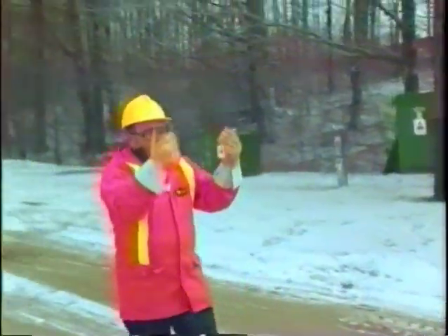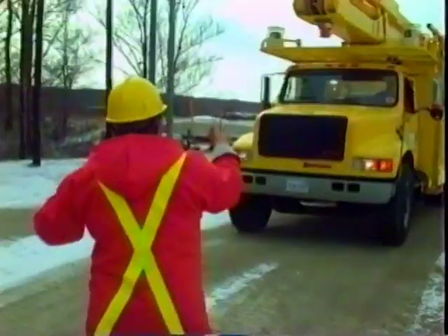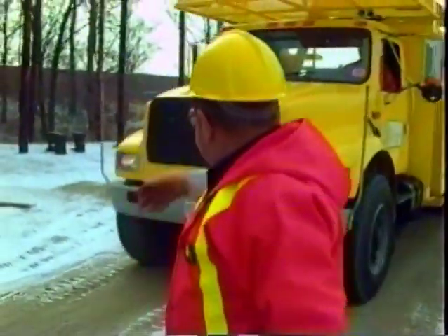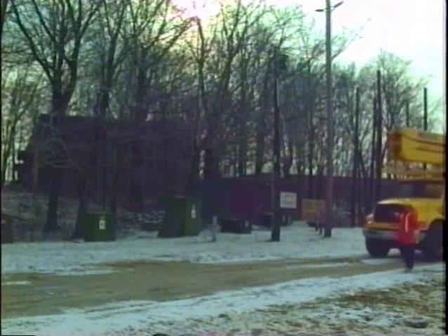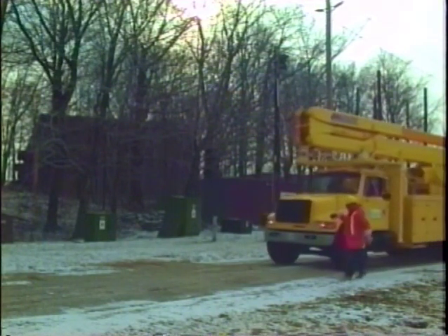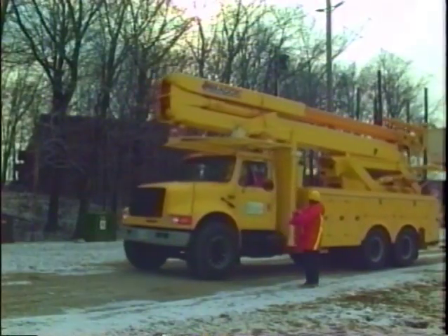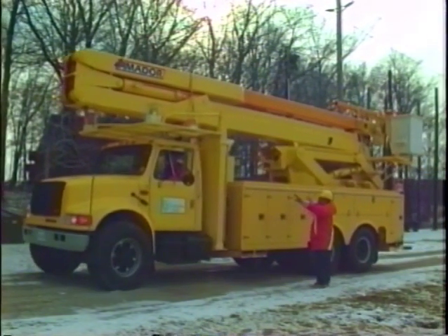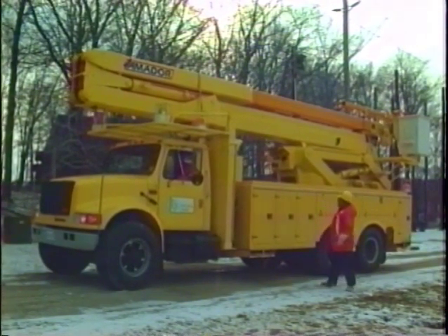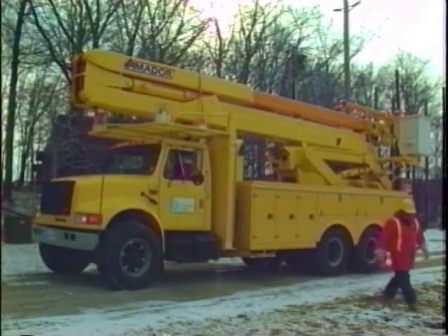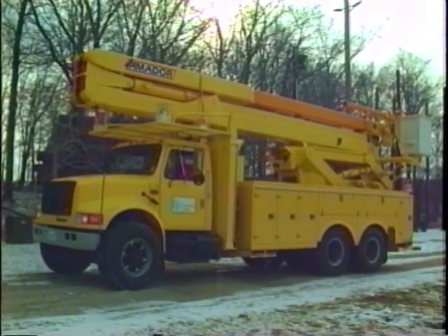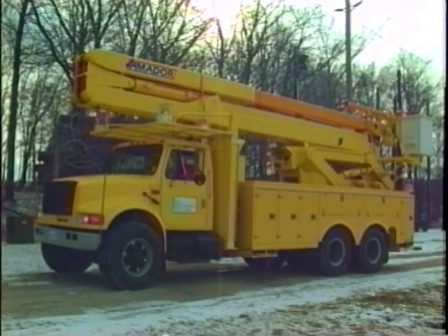It goes without saying, you should never work from a vehicle unless you are sure it is stable. There are 4 basic steps involved in making a bucket truck or an RBD secure. Start by positioning the vehicle properly. Do not park right next to a curb or a hillside. Leave enough room to extend the outriggers all the way.